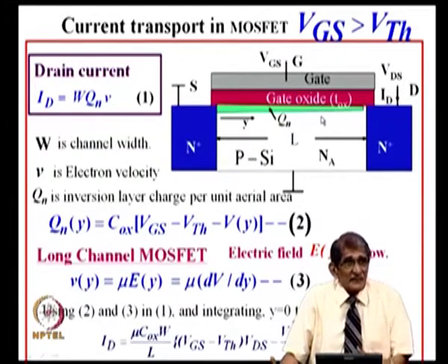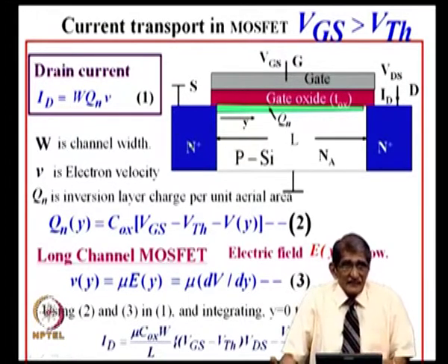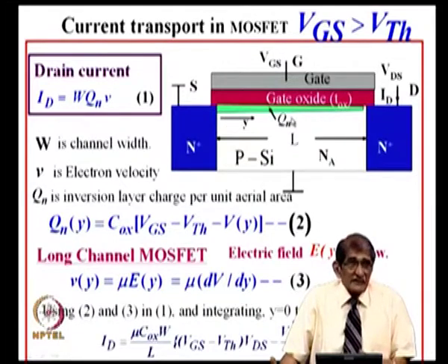What happens to the resistance value? It increases. Rho L by A. Okay. Rho is the same. Rho L by A, the area of cross section decreases. So, that means as you increase the VDS, the resistance does not remain constant, but keeps on increasing.